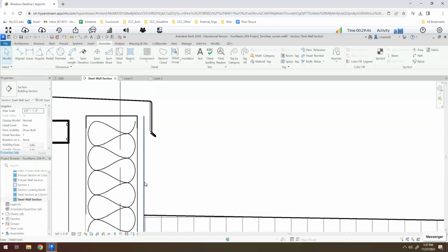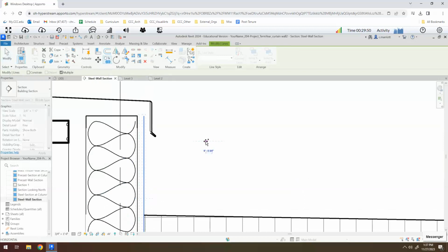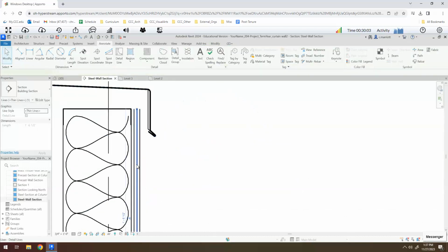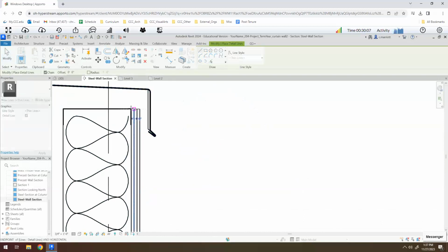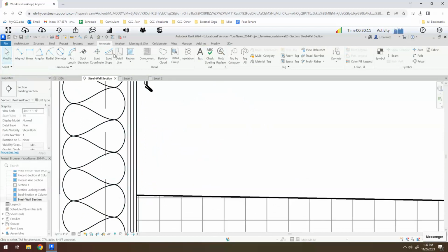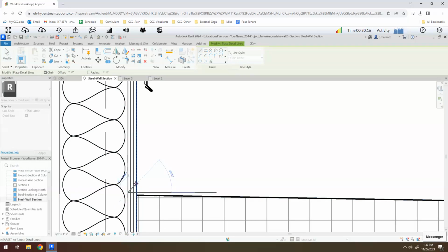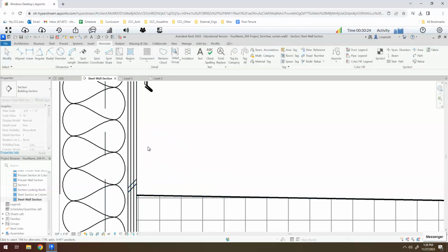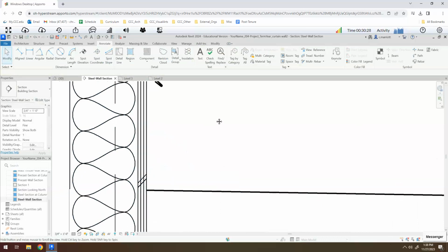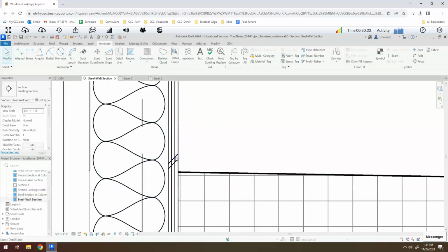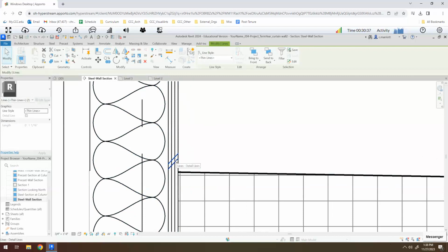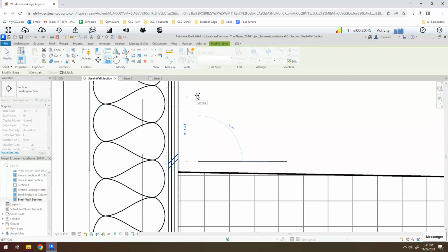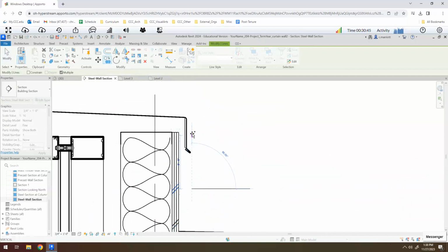Okay, now plywood, the graphic for it is typically a series of lines like what I'm drawing right now, 0.25 inches. And then the other thing that we do with this is draw a few diagonal lines. So I'll just make one here, 45 degrees, and I will copy this one up, let's say 0.375 inches. Something like that. Okay. And then I can hold the control down so I pick both of them, and then add a few more of these little graphic symbols.